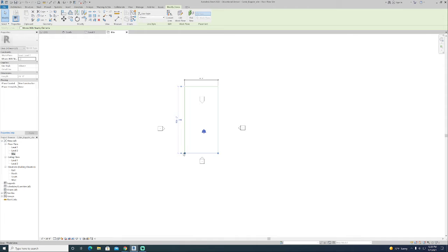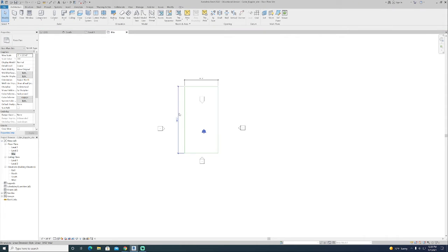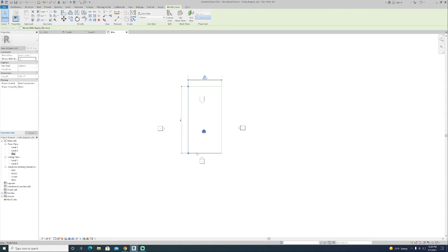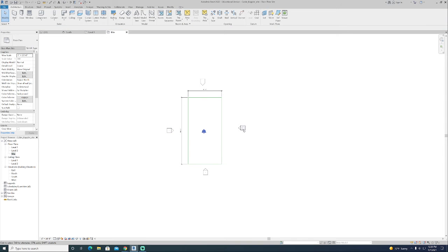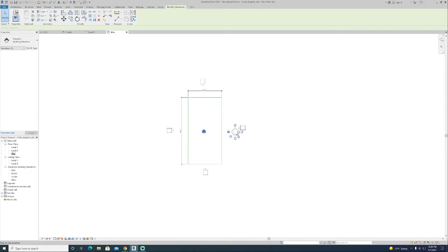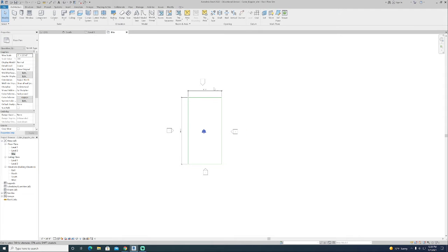Once it's in there, like I said, you can click on that little option to make it a permanent dimension. You can always lock it in place. Now when you move the rectangle around, whether up or down, the dimensions are always going to stay in place. And if you want to move those elevation symbols outside of the box, you can. But you have your project essentially defined, your topography defined width-wise and height-wise now with model lines.